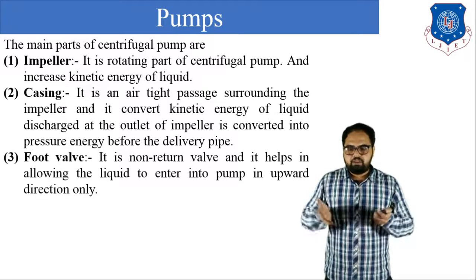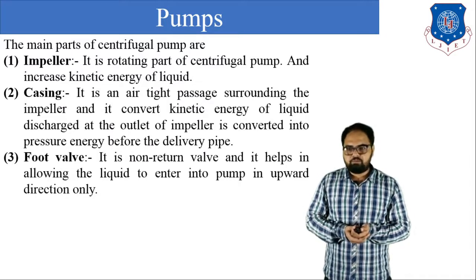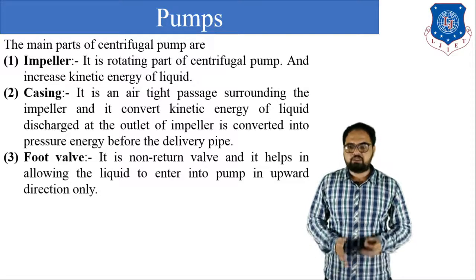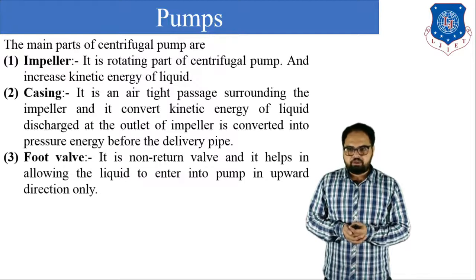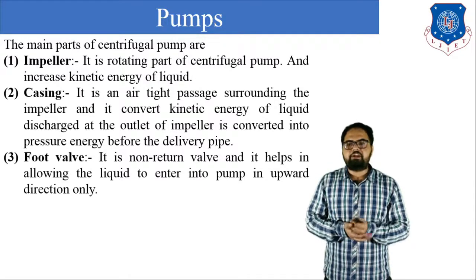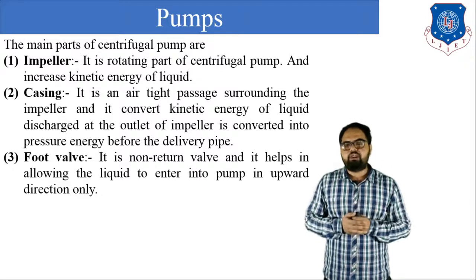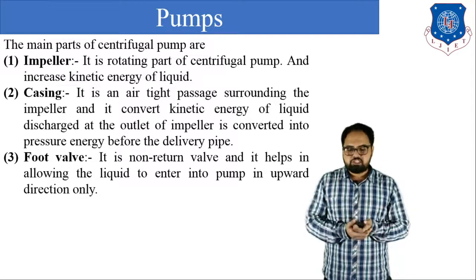The third one is the foot valve. The foot valve is a non-return valve which is fitted at the end of the suction pipe. It is always deep inside the water and it is used to prevent the backflow of the liquid from the suction pipe to the sump.